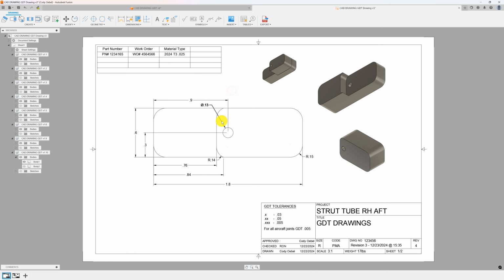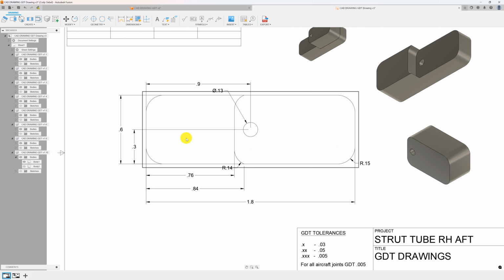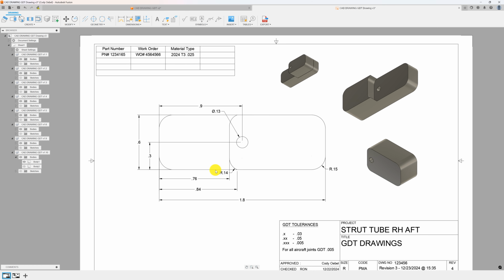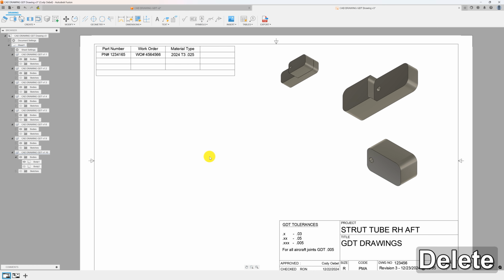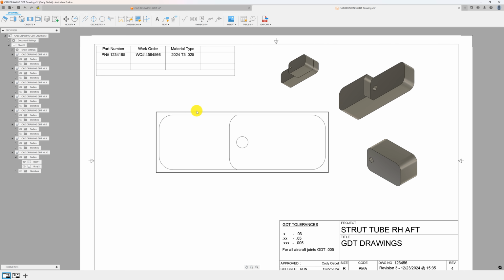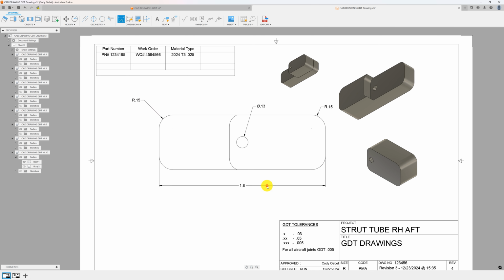So why is auto dimensioning not always the best? Well, what we call this in a machine shop is a lot of noise. A lot of this stuff we don't really need. It can be really simplified, and it can be simplified down. So let me get rid of all that noise, and instead we can dimension things manually. Overall dimension, and boom, everything is nice and clean.